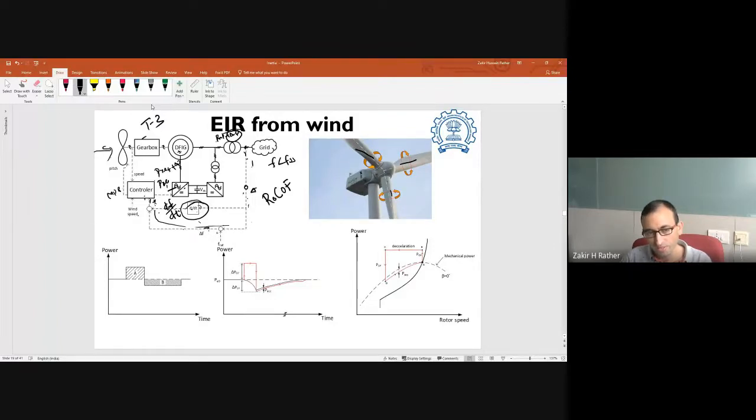So you can see here what is happening. This is the electrical power output of the machine. Because of the disturbance in the frequency of the grid, that is, the change in the frequency of the grid, this delta P, as I was mentioning, increases. But what you need to keep in mind is the mechanical power generated from this turbine, which is torque times omega, is going to decrease. This is mechanical power, right? Before the disturbance, it was generating torque times omega equal to MPP. But now, because you give a delta P signal to this controller, it started extracting power from the same concept. It releases additional power from this 1/2 J omega squared.